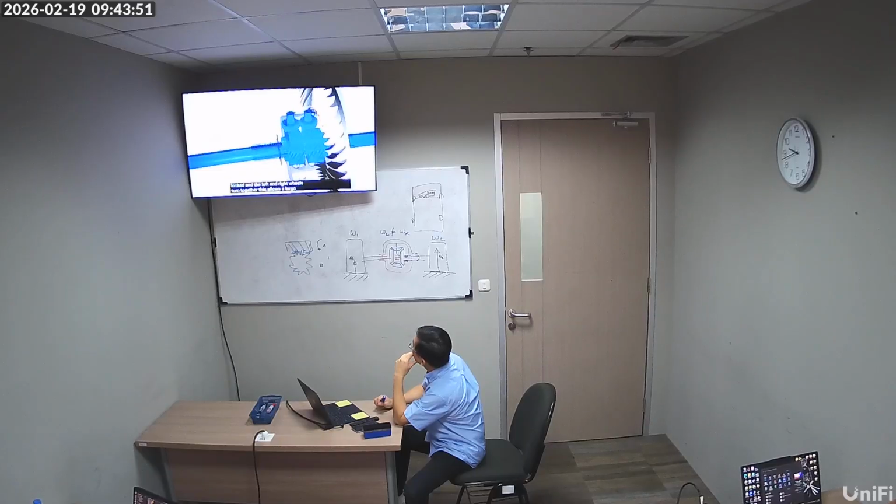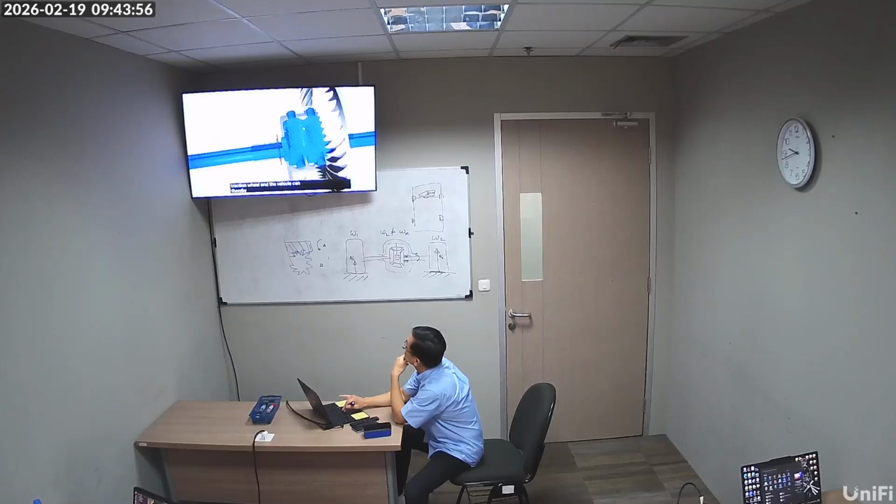This allows a large amount of torque to be transferred to the high traction wheel, and the vehicle can thereby overcome the traction difference problem. In fact, it transfers 100%, right? So this is even better than the clutch pack. But the downside of the clutch pack is that there is always some friction between the left and right, whenever there are slight turns. There is some, not much, but the torsion overcomes this perfectly with no friction mechanisms.